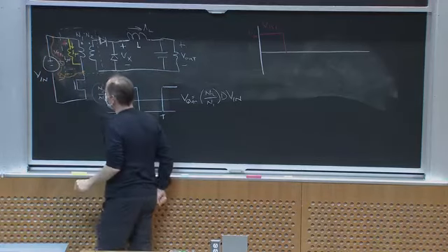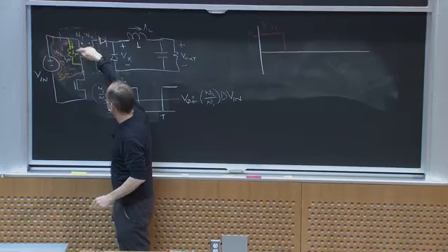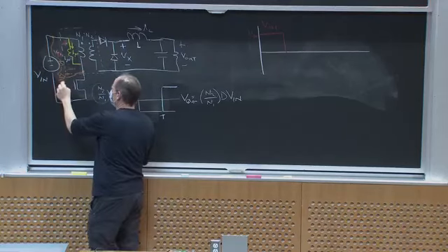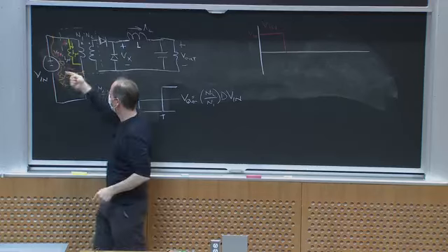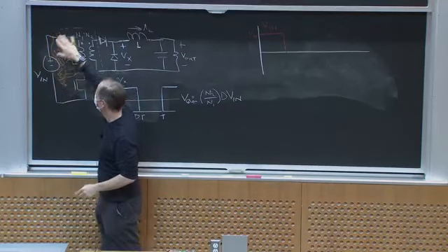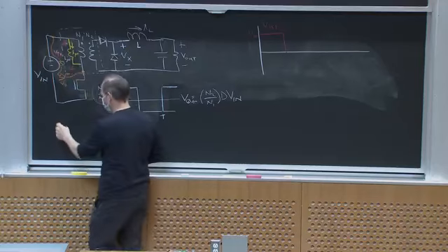And so what this does is this lets this magnetizing current flow into this orange path against some voltage, Zener voltage VZ, and back up here. Okay, so this orange path is another path for current to flow through.